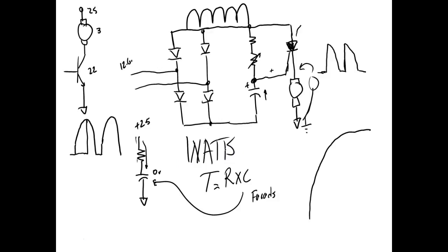You understand? So that means my transistors are going to have to be extremely high powered to try to run a motor. But this guy right here, you either turn it on or off. So when it's on, it's dropping very little voltage. When it's off, there's no current flow through it, right? You understand? Just leakage current. So that means I can control a motor. So this right here, this wattage right here is wasted. What work is that wattage being dropped across my transistor doing? Well, it's creating heat. It's not running the motor, so the motor's getting very little power, but I'm consuming a lot of power, right? You understand?